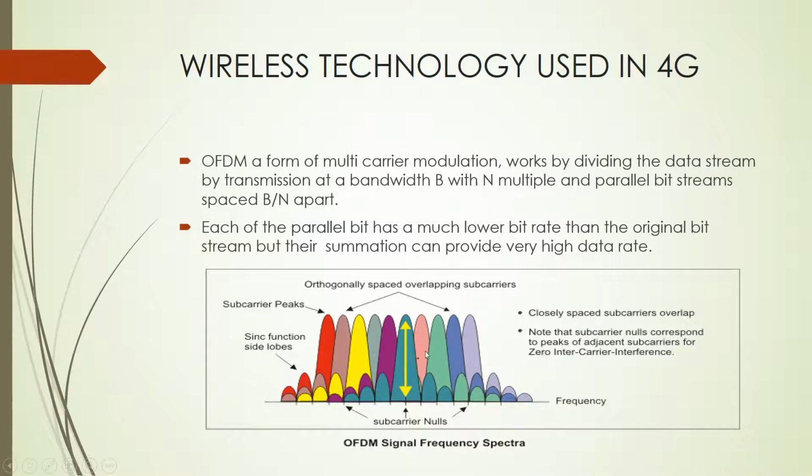The main aim of OFDM is to send low-rate modulations in a parallel stream rather than sending a high-rate wave front. As low-rate modulations are less sensitive to multipath, with OFDM technology already proved and embraced, 4G development will gain momentum.